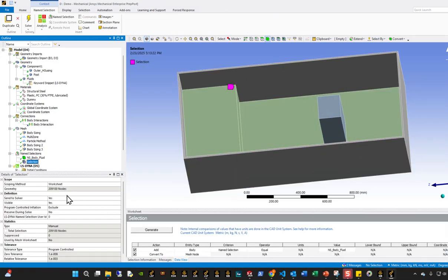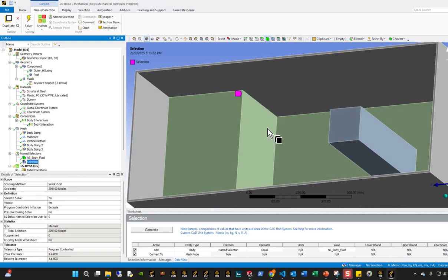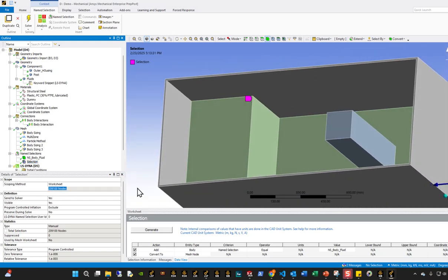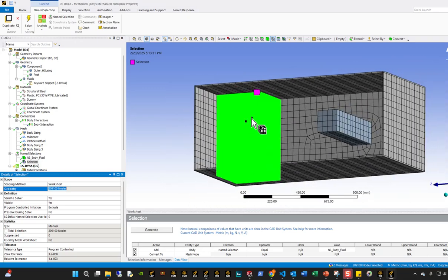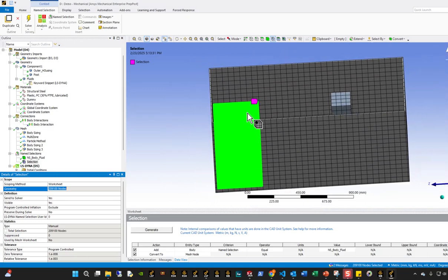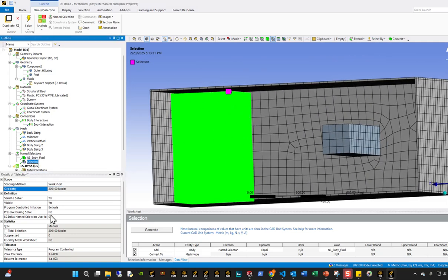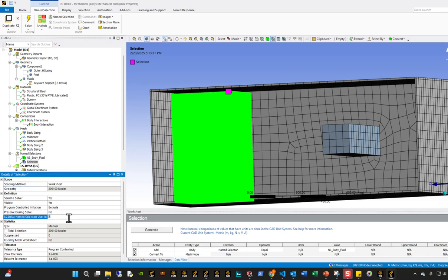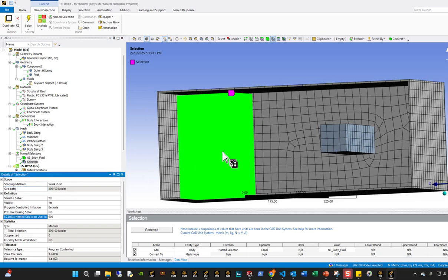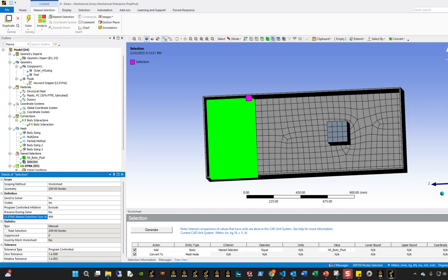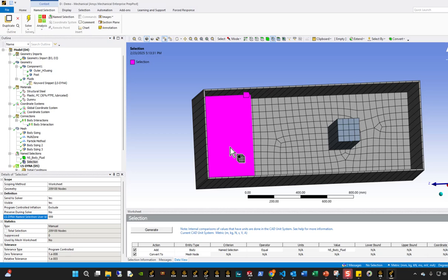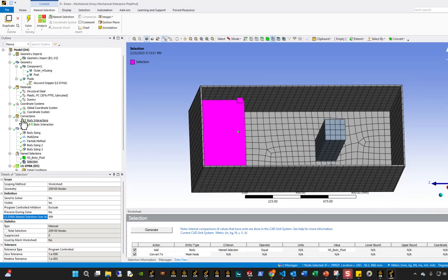And that's going to create these 200,000 nodes right here. You see all those nodes right there, they're going to be scoped to all the nodes on that body. And then I'm going to create a name selection ID, a body ID called 999. This 999 is what I'm going to use to define contact between these nodes and the two different bodies that we just talked about, right?